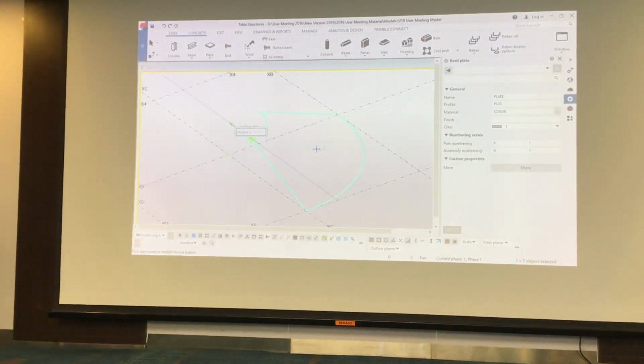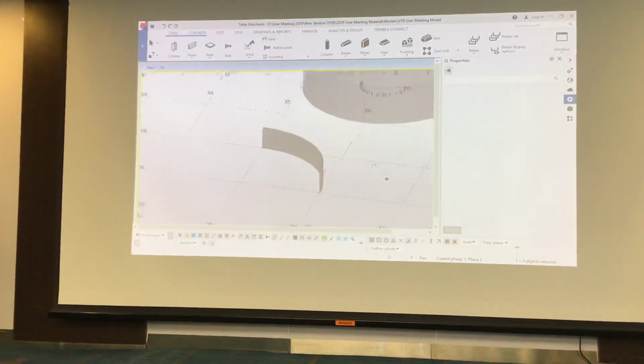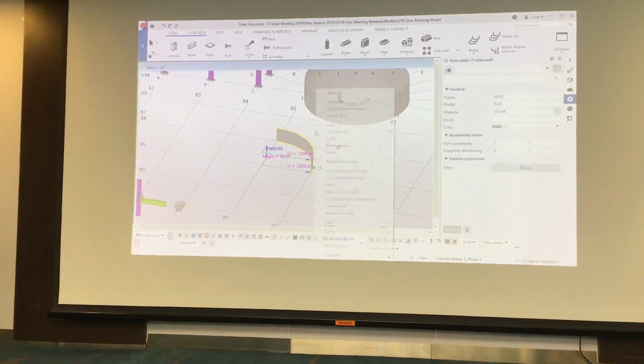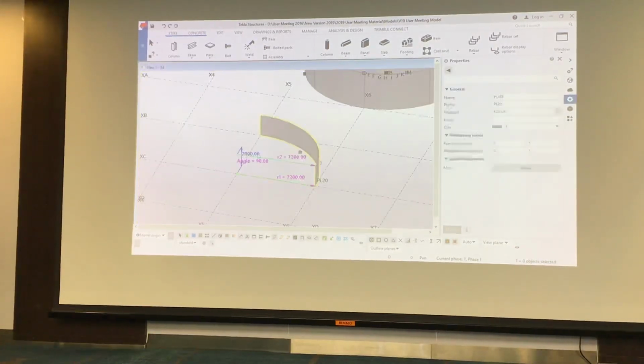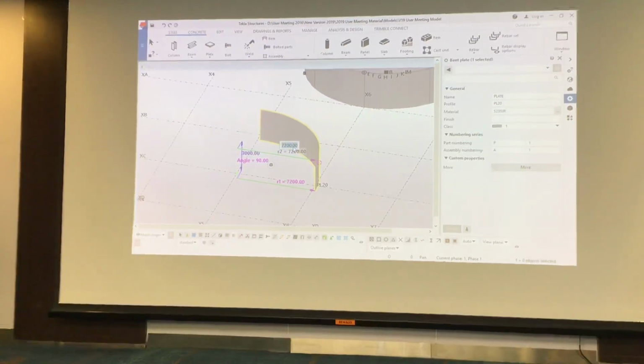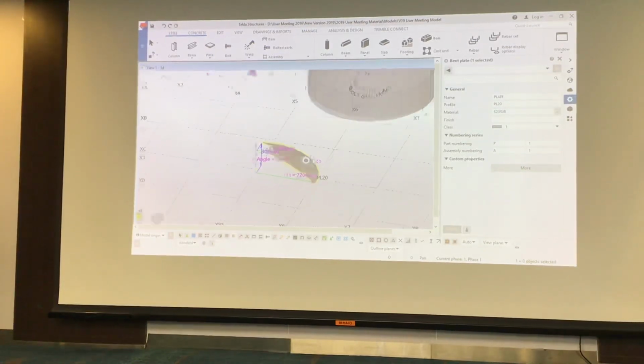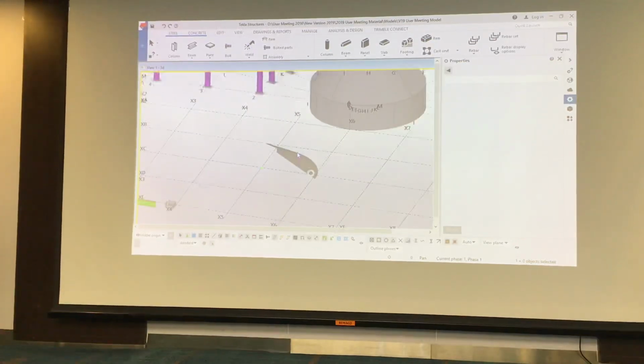And then look, you can actually determine what the shape of the cone is. Can you see it? But in this case, I'm going to say, look, I just want a straight plate like that. And then we can pick that up, and we can look. And then when you do that, you can click on these points, and you can say, look, the height is 3 meters. Okay, the radius is, well, let's make it 2 meters. So you can change all of these points, like so. So you can easily manipulate it.